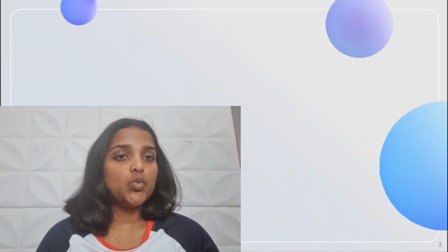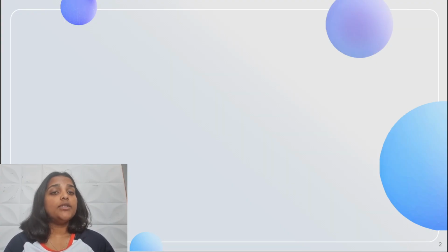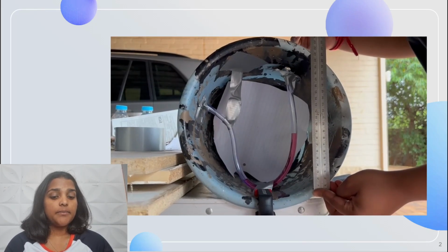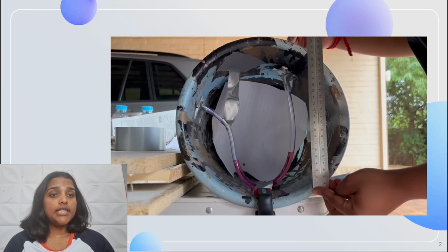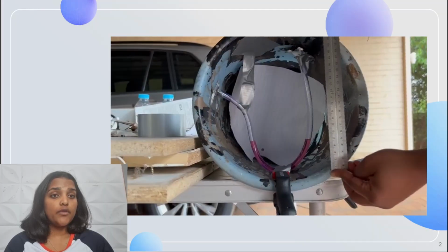Once the apparatus was assembled, it was carefully inspected for leaks to ensure accurate pressure readings. The U-tube was filled with water to an equal height on either side of the tube before an airflow was introduced. The airflow was obtained using a hairdryer to simulate low flow speeds and a leaf blower to simulate high flow speeds. For each airflow setting, a height difference between the 2 columns of water in the manometer was observed.